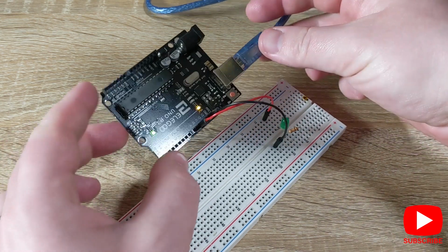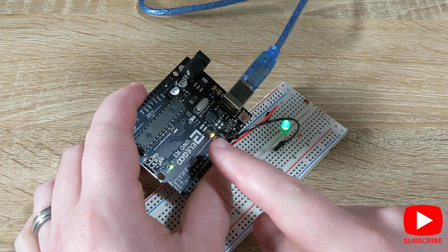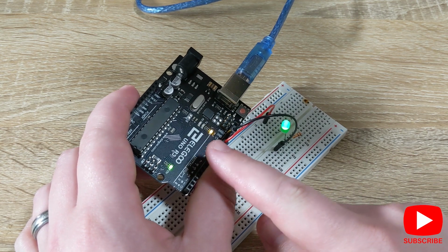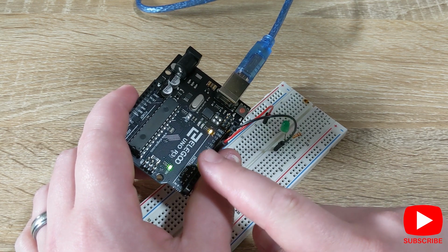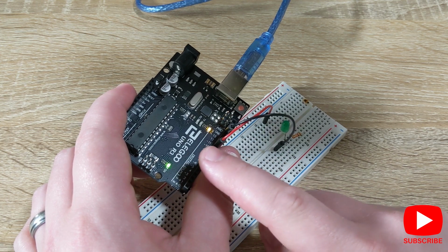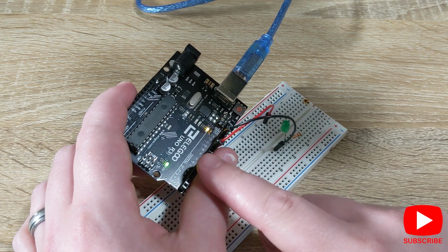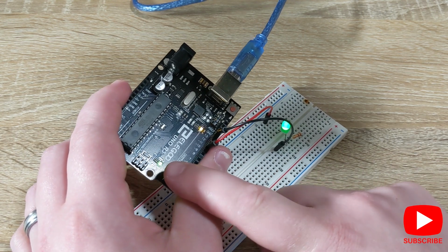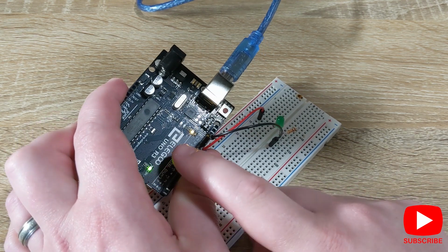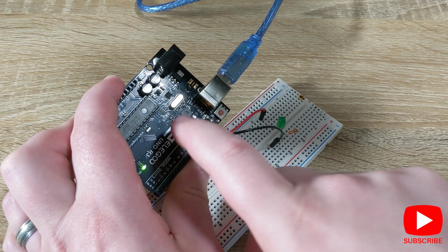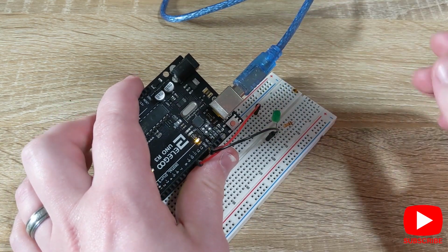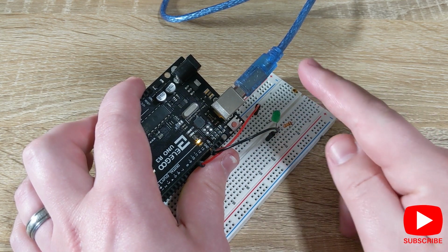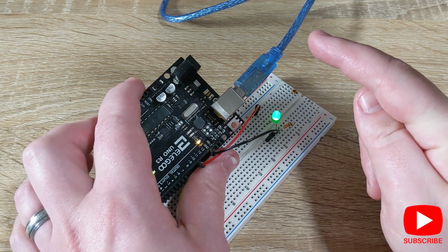On the Arduino itself here, that little orange LED that's lit up is the LED on pin 13. I think that must be just set to high by default. But if you wanted to turn that off, you could do that in the void setup. Just set that pin 13 as low. This other LED here is the power. These two LEDs here are the transmit and receive LEDs. Now, these can be really handy to know if you're communicating between your computer and your microcontroller.